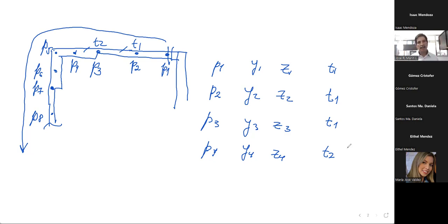In the definition of the tracks, my suggestion is do not include, especially on the sides, simply 2 points. Because internally, what the program does is it starts doing these integrals to calculate the first moment. All of these calculations are performed numerically, right? Especially on the sides, the variation is not linear. If you put 1 point up and 1 point down, basically you are going to do a linear interpolation. So the integration will be poor.